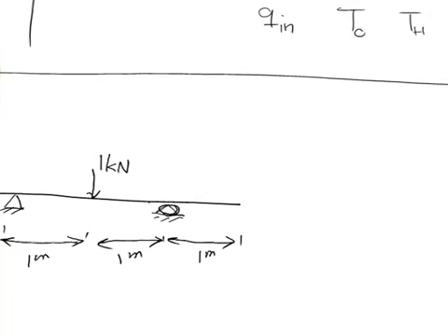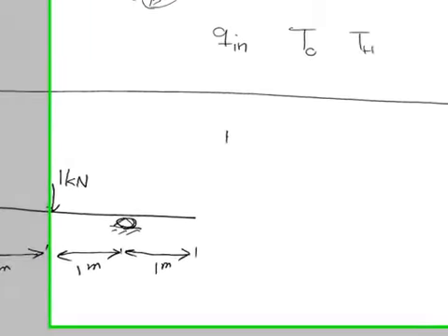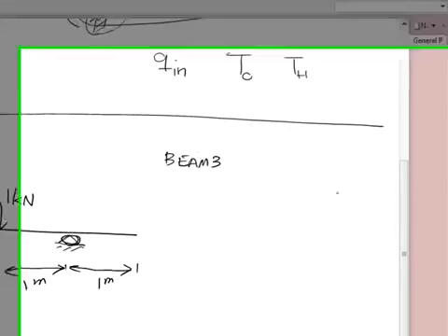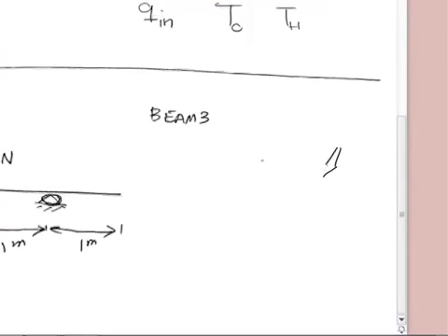Basically, what I have to do is to define an element first. For this case, I'm going to be defining the element BEAM3, which is a very basic element in ANSYS, which I've heard that some newer versions of ANSYS are not supporting anymore. There is an alternative way, which I will explain later in future examples and tutorials. For this beam, I'm looking for a square cross section of 12 by 12, let's say meters or units.